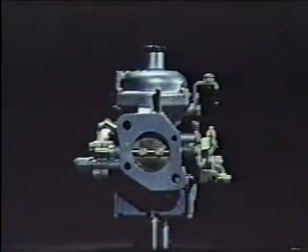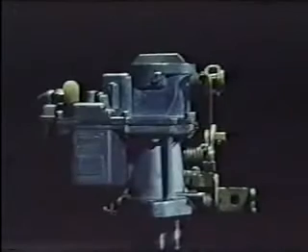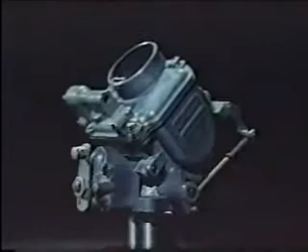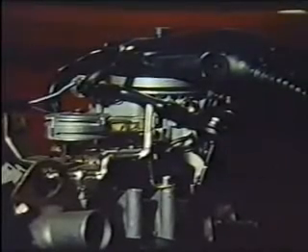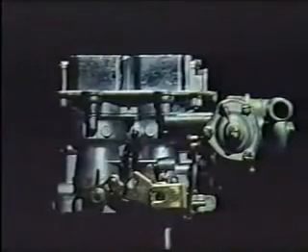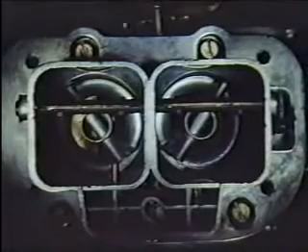The carburetors we have described are only two of many kinds. Although the principles are the same, individual engine requirements have produced many modifications of design and manufacture. In higher performance motor cars, maximum power is obtained by drawing in as much mixture into the cylinders as possible. A single carburetor is not always sufficient for this purpose. And one development which meets the need is the twin choke carburetor. It consists of two carburetors of different diameters side by side in the same casting.